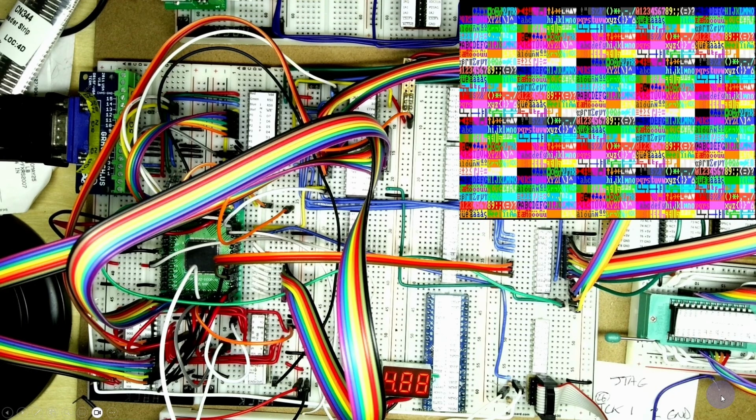Welcome to breadboarding. In the previous video we managed to get our CGA video controller working with the video attributes. So here's a test pattern that we produced, which has a repeating pattern by driving the video attributes from the address lines for the cathode ray tube controller. So you can see that the character generator input here is coming from the address line to the CRTC, as is also the video attributes input into here.